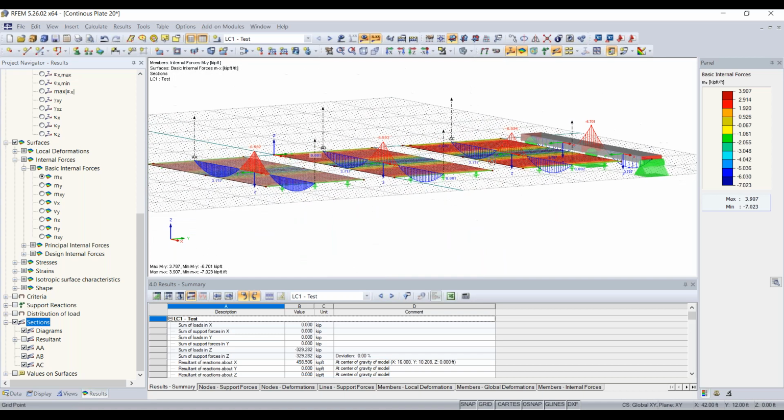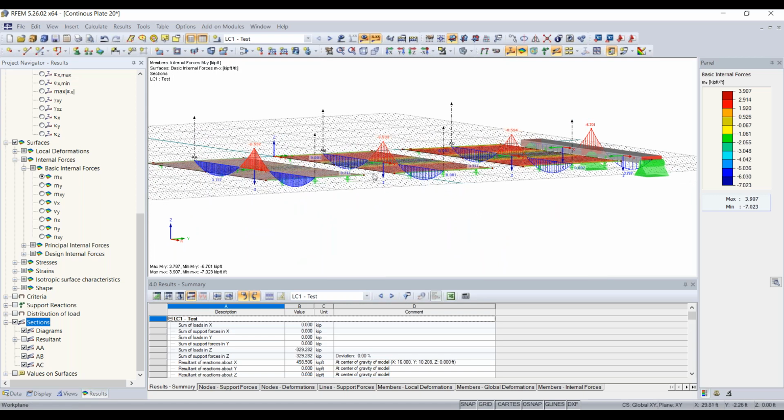on our plates here. And maybe now you can also see the difference in accuracy between our plates here, depending on the FE mesh size we chose. So this first one was 0.2, and then we increased the length between all of them. So that's showing you how the results and accuracy can change.